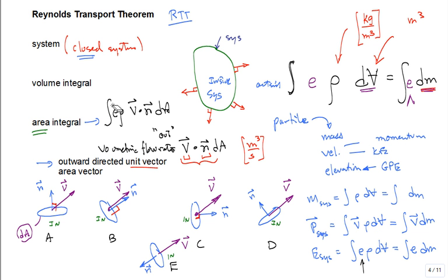One other thing you can do, what's this, P? Linear. You can have a linear momentum flowing with that mass in or out of the control volume. What would I put right here? Would I put a velocity? Yeah, the velocity is already in there. That's why when you see these equations, you scratch your head and say something must be wrong, because it looks like the velocity is double counted. But let's take it out and go slowly. What is that integral by itself?